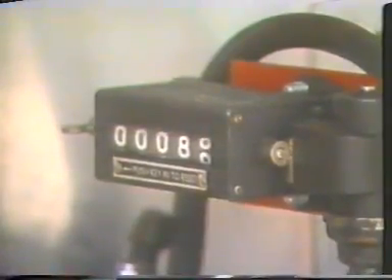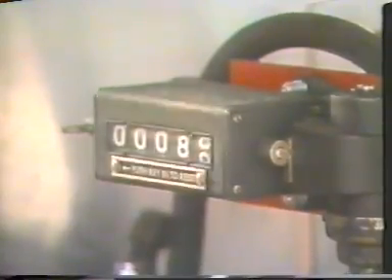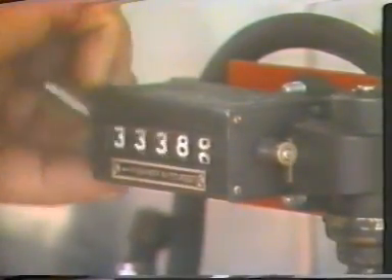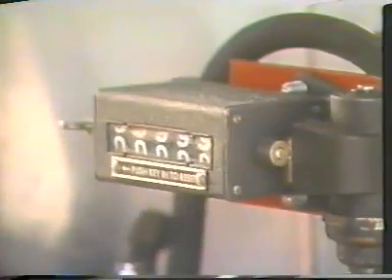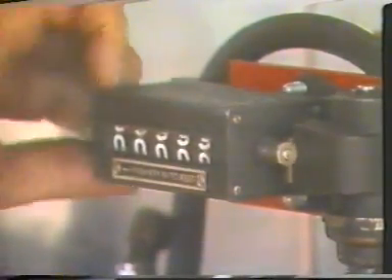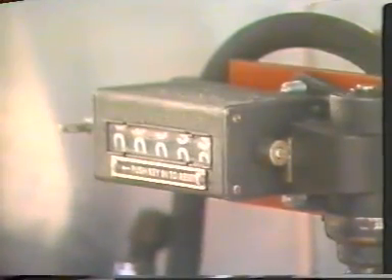The feeder root counter is attached to the shaft of the counter wheel either directly or via a cable, similar to an automobile speedometer cable. It is geared so that each revolution of the counter wheel counts off 2 feet on the counter. The counter has a key which allows the wireline specialist to zero the counter before lowering the tools in the well. The weight indicator tells the wireline specialist the weight or tensional force that is being pulled on the wireline.